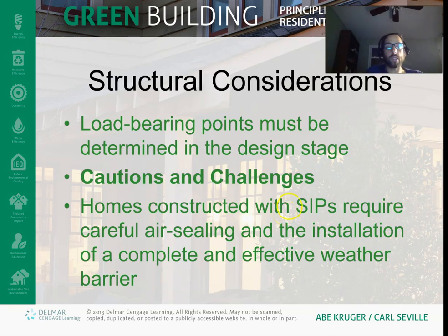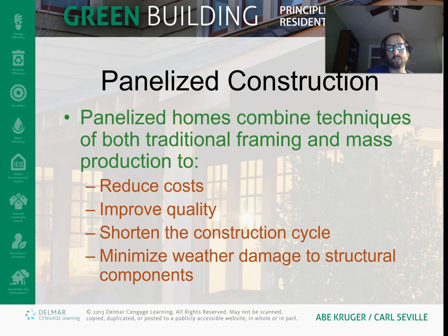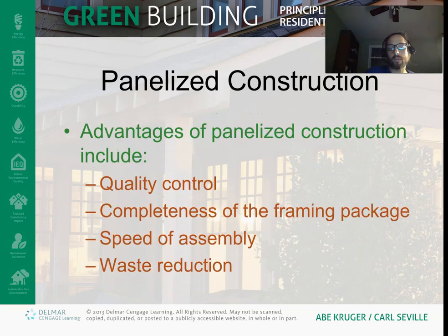So SIPs, just like anything else, you have to be really careful. They are structurally sound, but they're not the traditional framing, so you have to be a little more careful and have special training to design a SIP house. They can be quicker to put together, and it reduces the waste.